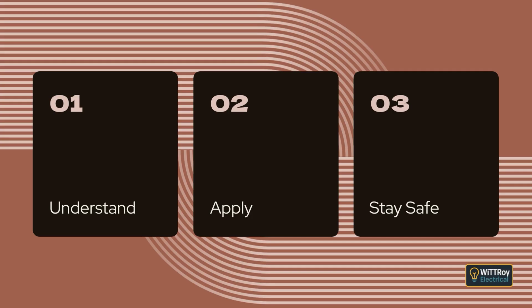Clause 3.11.4 Installation requirements. This clause outlines how underground wiring must be installed to remain safe from mechanical damage and environmental effects. Clause 3.11.4.1 General. Underground wiring must follow the specific requirements of the later subclauses, which include bedding, mechanical protection, minimum depth of cover, and correct identification.